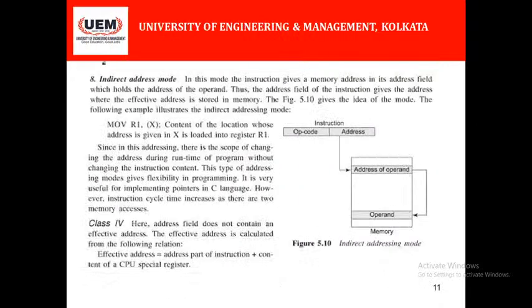After memory direct addressing mode, we have the memory indirect addressing mode. For example, say MOV A, M. MOV is my opcode here, and A and M are the operand locations. It indicates that M is my source operand location, and A is my destination operand location.